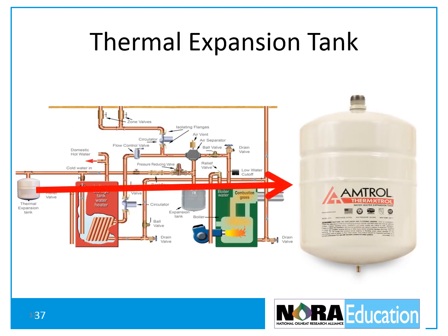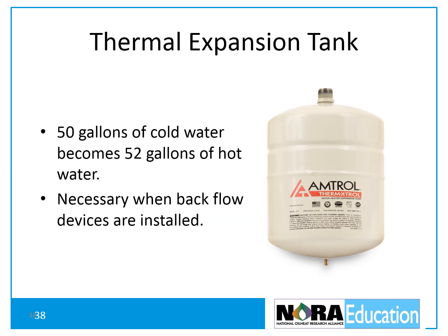Thermal expansion tanks. Domestic water expands when it's heated, and 50 gallons of cold water becomes 52 gallons of hot water. Thermal expansion tanks will take up the excess water, preventing continual discharges from the relief valve.